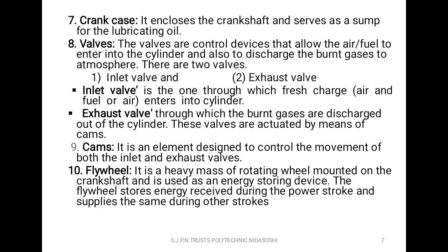Valves: there are two valves, the inlet valve and the exhaust valve, which control the flow of air fuel mixture into the cylinder and exhaust gases from the cylinder to the atmosphere. The inlet valve is the one through which fresh charge, air only or fuel air mixture, enters into the cylinder. The exhaust valve is the one through which the exhaust gases escape to the atmosphere from the cylinder. These two valves are operated by cams. Cam is an element designed to control the movement of both inlet and exhaust valves.